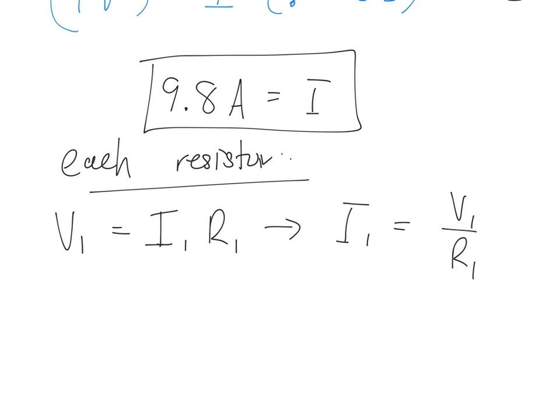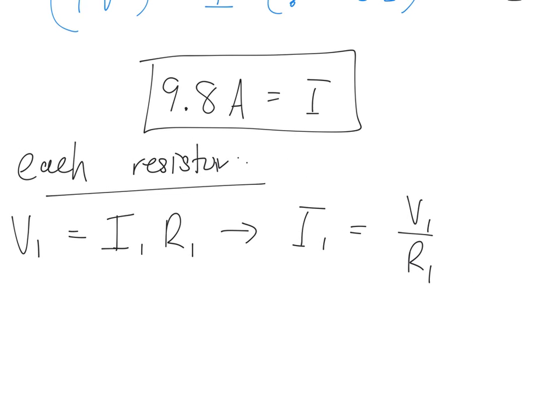Because everything is the same voltage in a parallel circuit. Look at your parallel circuit law. V1 equals V2 equals V3 equals the voltage from the source. The voltage across any resistor is equal to 9 volts in this setup because it's in parallel. In parallel, all voltages are the same. So this becomes a pretty easy problem to solve now. We're going to get 1.3 amps.